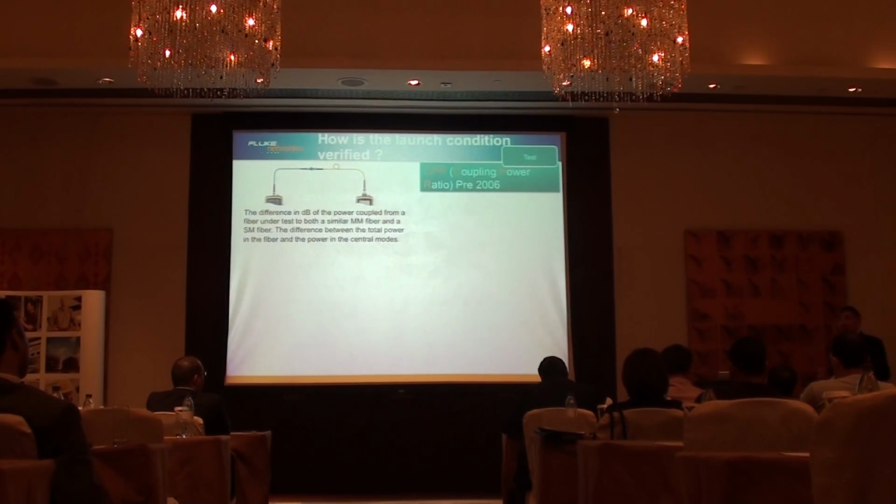And they would certify that you had a CPR1 from Fluke on your fiber tester to be able to do a proper testing. This is the first thing that they did. This is pre-2006. Now, with the introduction of gigabit Ethernet and running fiber on gig, they saw that the results were not repeatable. That means you're not getting the same results. There were just way too many issues with the results.